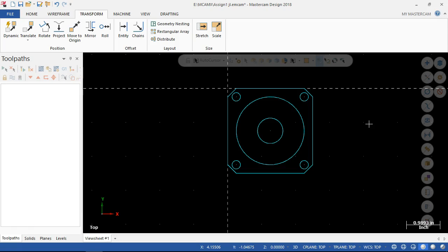So we're going to talk about the difference between a roughing and a finishing pass, because they're basically the same operation. It's just, are we going to step and repeat, leave compensation? And what happens when I've cut all of this stock and most of it is, say, 60 thousandths over in X, and the saw cut's pretty rough and angled and whatever.